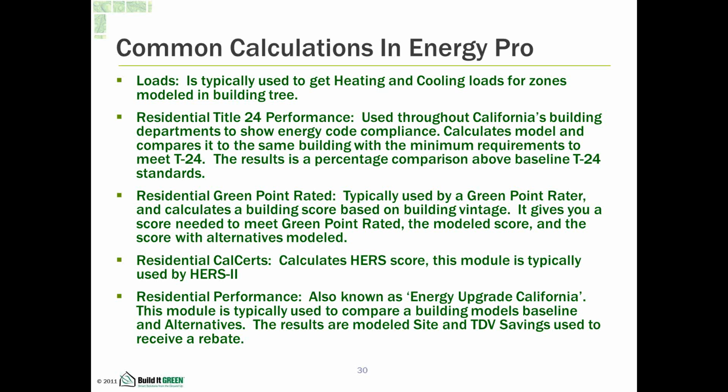And your building at test in or test out will either meet or not meet, or should meet or beat the Greenpoint Rated target index. The CalCerts module gives you a HERS score. I don't think this is approved for multifamily, but I think that's good practice to just enforce what the HERS score is, and maybe get people thinking what a HERS score would look like for a multifamily building.